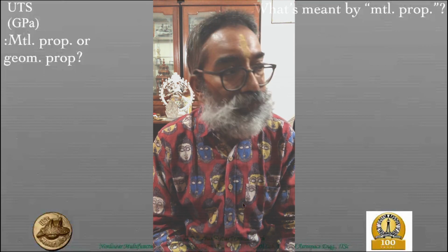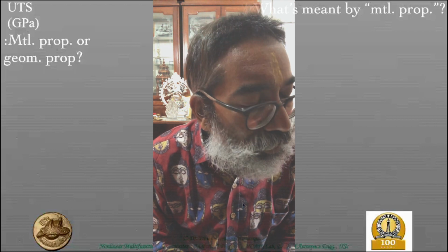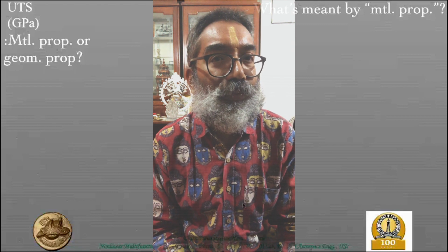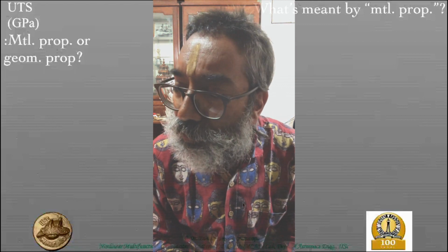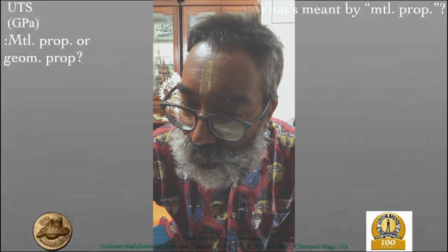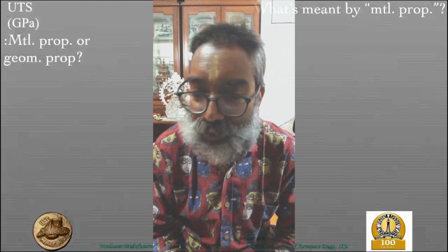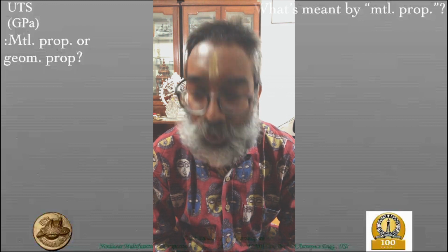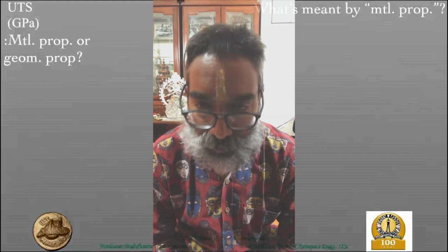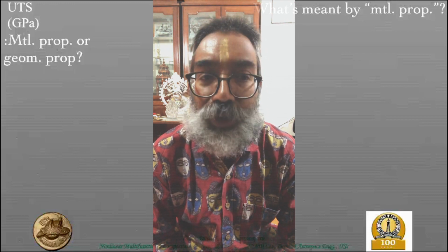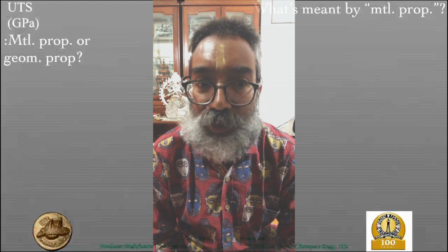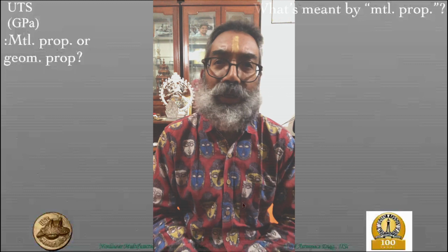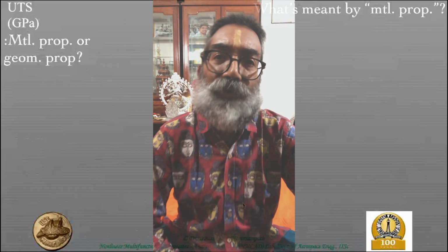Come again? I couldn't hear you clearly. Sir, Akshay this side. The ultimate tensile strength will depend upon the direction also, in which direction we are taking it. If the microstructure is elongated, say in a rolled section, along the rolling direction it will be different, and in the transverse direction it will be different. Excellent. So it is directionally dependent. It's anisotropic, but let's leave that for now.